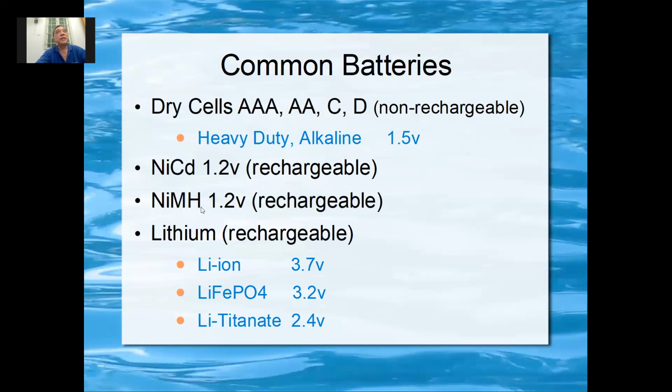So this nickel metal hydride will also become obsolete. It is getting less popular nowadays. And all these are AA and AAA type. So when it comes to lithium, the main problem with lithium is that it's 3.7 volt. It's not 1.5 volt. So it cannot be used as a direct replacement for your existing battery.